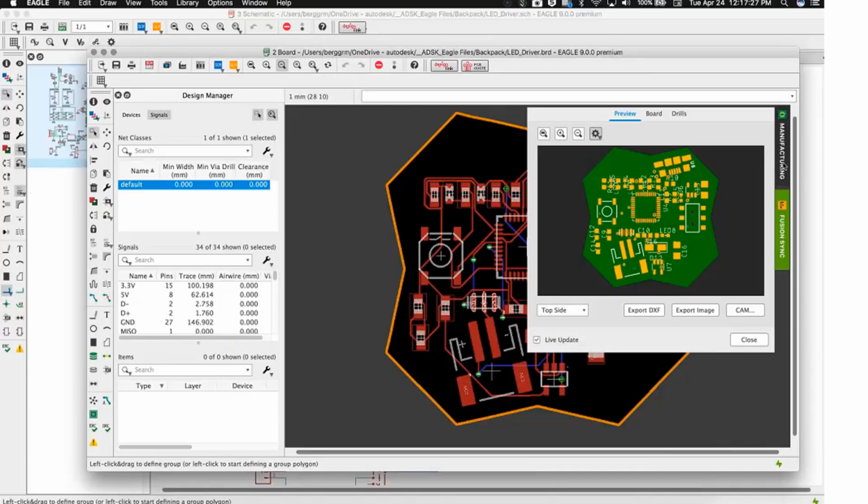And that's something for us to explore. But Eagle's arcs today are basically slices of a circle. And so there are limitations in terms of what we can do with things like elliptical arcs, those sorts of things. If you explode splines within whatever the original authoring tool is, then it's going to approximate those arcs. The problem you can face with that is then the endpoints are not necessarily coincident. And that can create some problems in terms of calculating the board shape boundary. But there's work that we can do on that front to improve board shape in general.